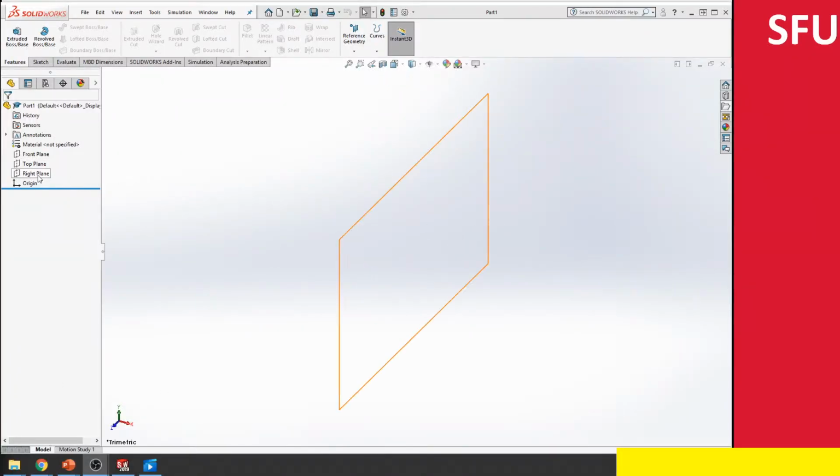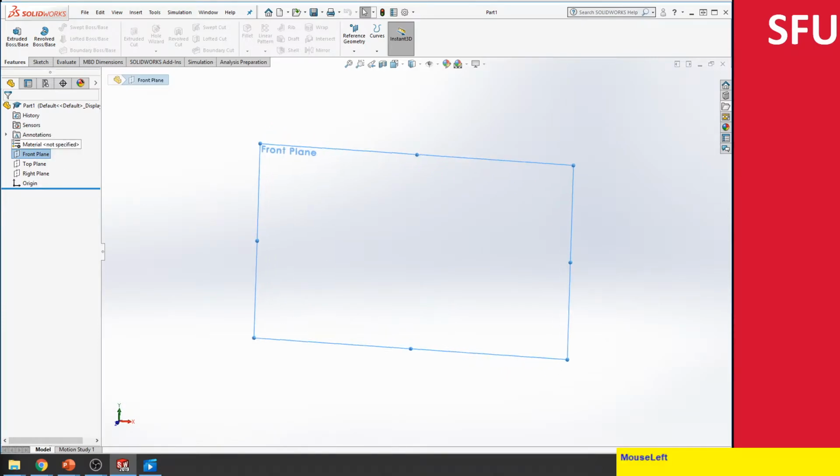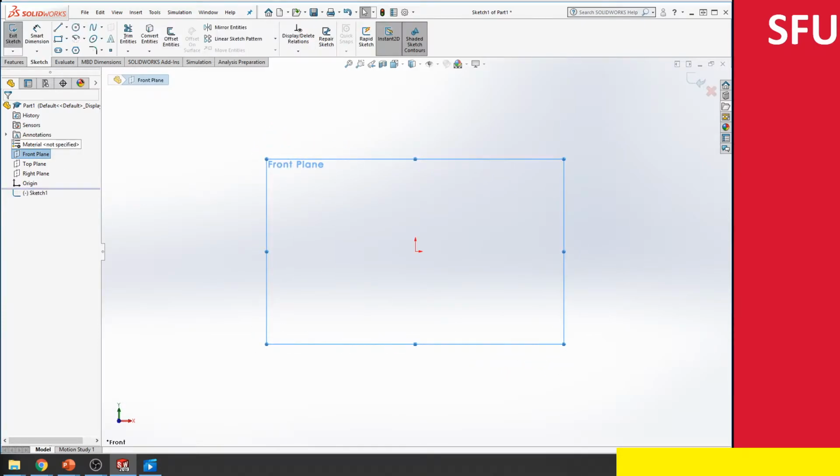So let's look at SolidWorks. Imagine I want to create the sketch on the front plane. So I would click on the front plane. As soon as I do that, it opens up a context menu right above. Here I'm going to move the mouse. It gives me the hint, and then I can click, and then it creates a sketch. You notice that the orientation of the plane changes, and then you have a couple of things here. This is the axis, which tells you how your scene is oriented, and this is the axis corresponding to the front plane that you're drawing on.